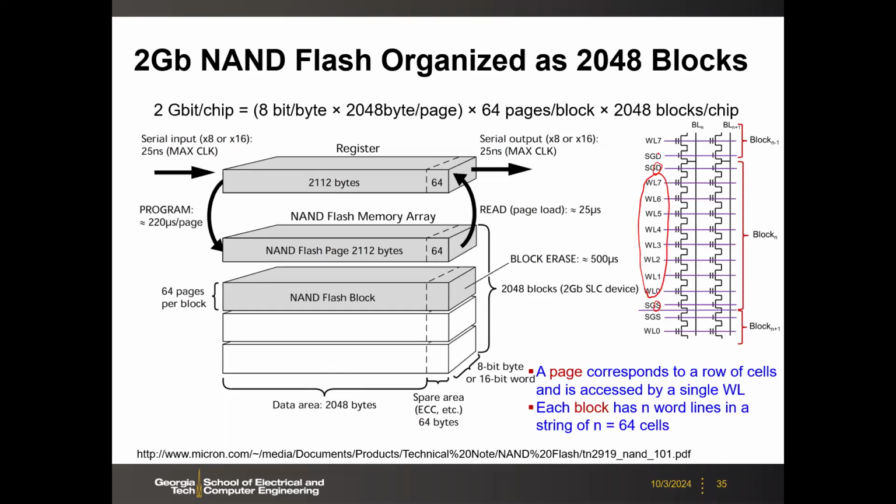So here then, typically this is how the NAND flash is organized into the array. So you may have like 8 bits, 8 strings, as 1 byte, okay? And then here the number of strings within one block is very large. So you may have here like 2 kilobyte bit lines or 2 kilobyte strings per page. So here the term page actually means one row or one word line. It's the same thing. Okay, in the NAND flash, it's the same concept. One page is one row or one word line.